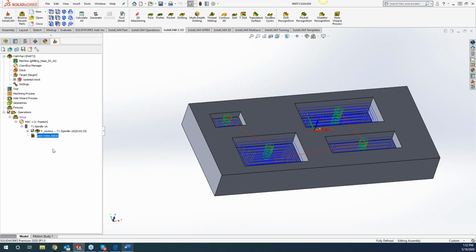And what that will do is it will insert my notes right here. Now, what will happen is if I go to G-code this out, this is going to be included as part of the G-code. So what I can do is put those notes in parentheses, so it doesn't come through the G-code or as trying to read the G-code, but you can put notes in here.